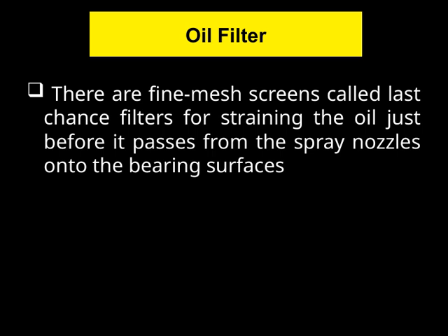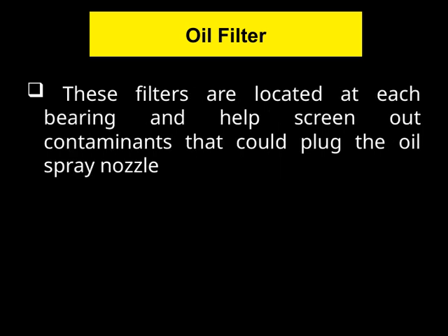Think of these last chance filters as the final line of defense, ensuring that only clean, filtered oil makes contact with sensitive components. Incorporating this extra layer of filtration is a key aspect of good maintenance practices and helps us keep the system running efficiently and reliably. These filters are located at each bearing, and help screen out contaminants that could plug the oil spray nozzle.